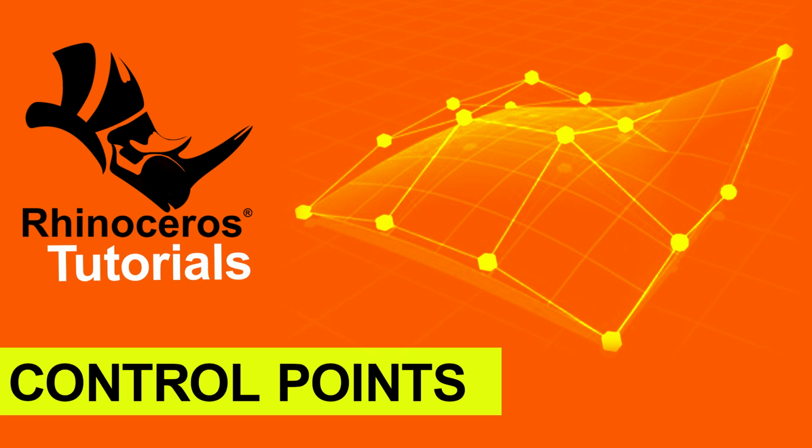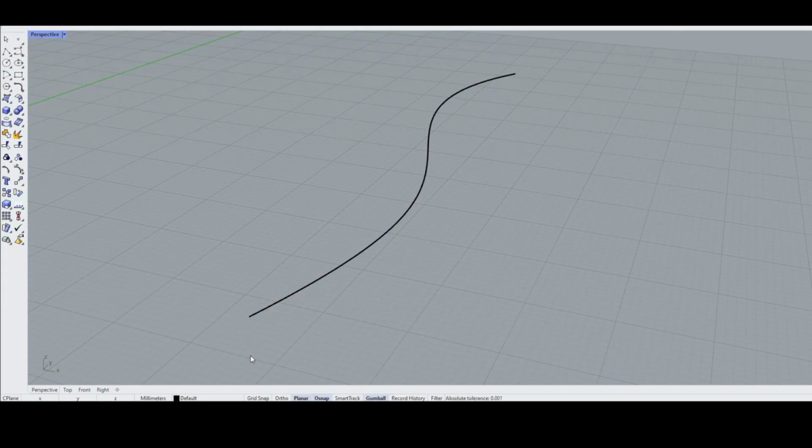Hello everybody, this video is about selection of control points and edit in Rhino. Let's start. The first thing I'm going to do is create a surface using Sweep One Rail. I would like to use this curve as a rail, and a circle at this end as a cross section.